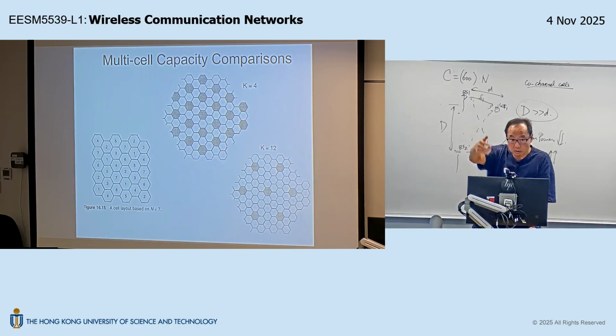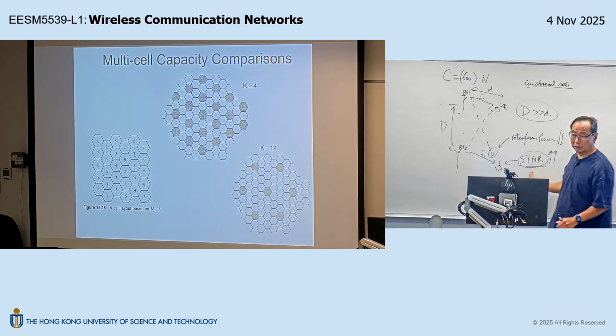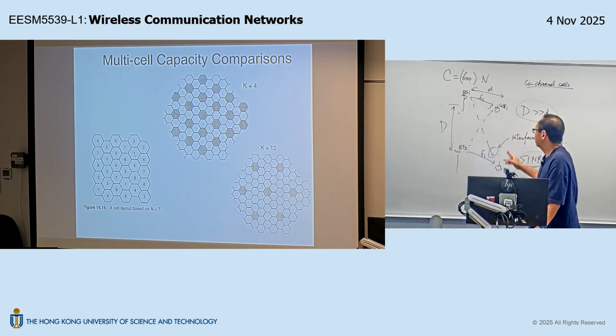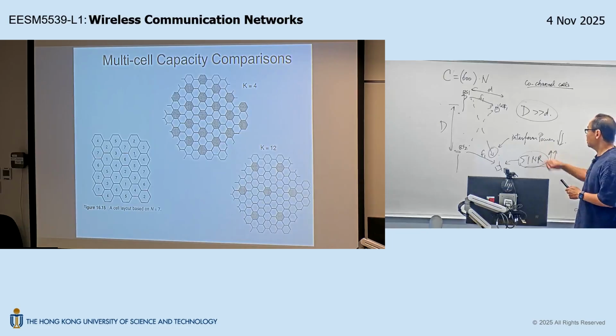But now the crosstalk will be much weaker compared to my voice. So your SIR would be much higher than before, right? Likewise for the other side of the class. Is that okay? So that's why we say that path loss is your friend, because the fact that this interference power is reduced is due to path loss.